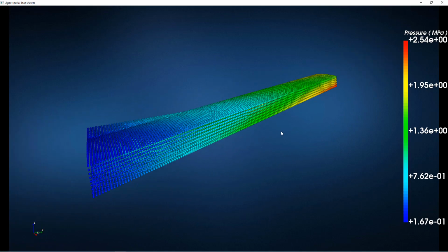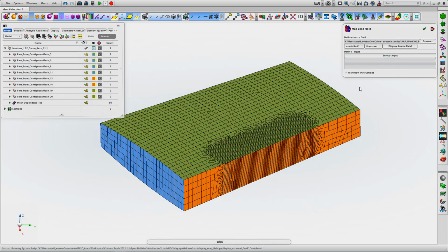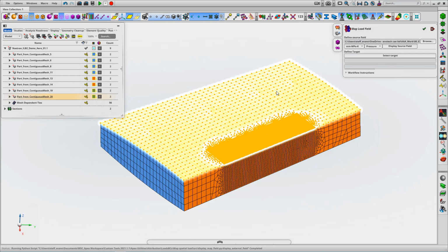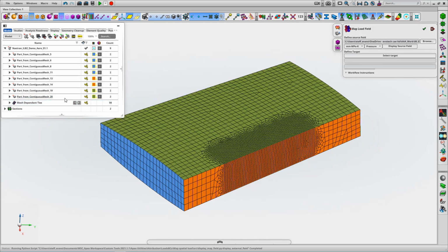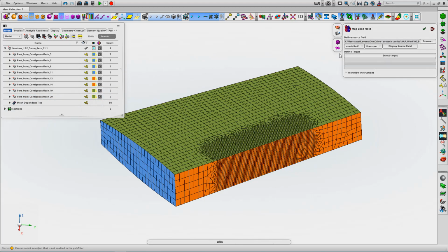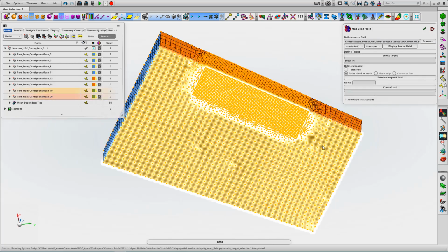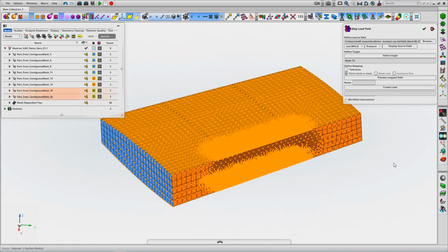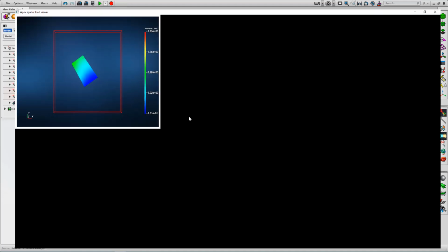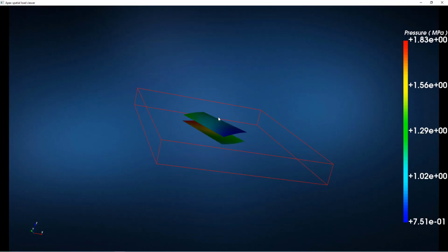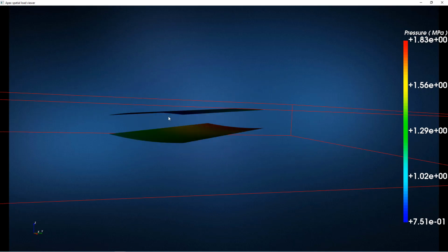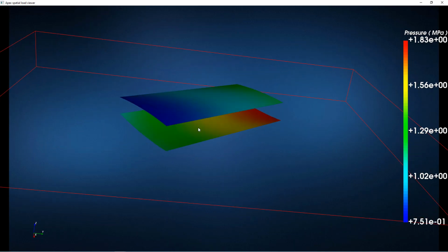We can come out of this visualization tool and then specify the regions of the model where we might want to define the new pressures. So we're going to look at the upper and lower skins, just selecting those. Okay, so you can see those. We can preview the map field. This is like a zoomed in version of the data that we showed previously. This is how the pressures will appear on the structure. So we can look at the distribution and the scalar quantity for those pressures.